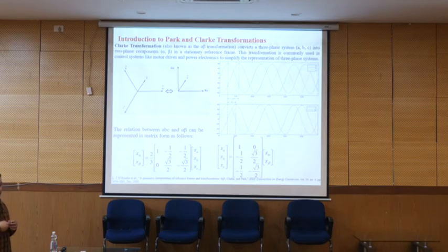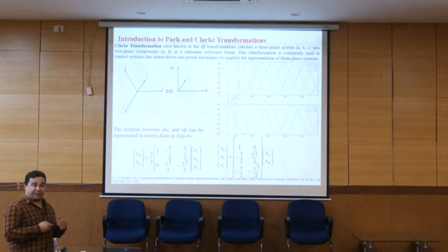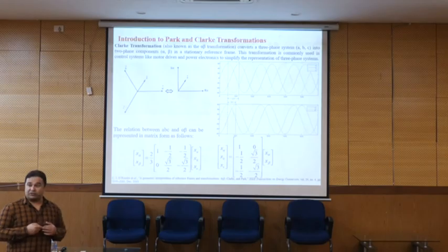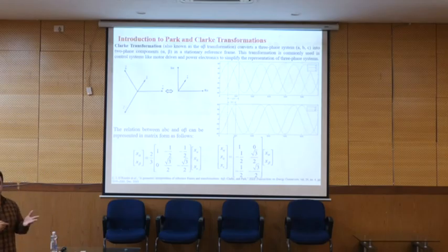So the benefit of this is like a complementary side of the DQ. There are some benefits in alpha beta in comparison with the DQ, but DQ is more flexible because we can separate the fundamental frequency from the variable frequency, and then compensation is much easier for us.